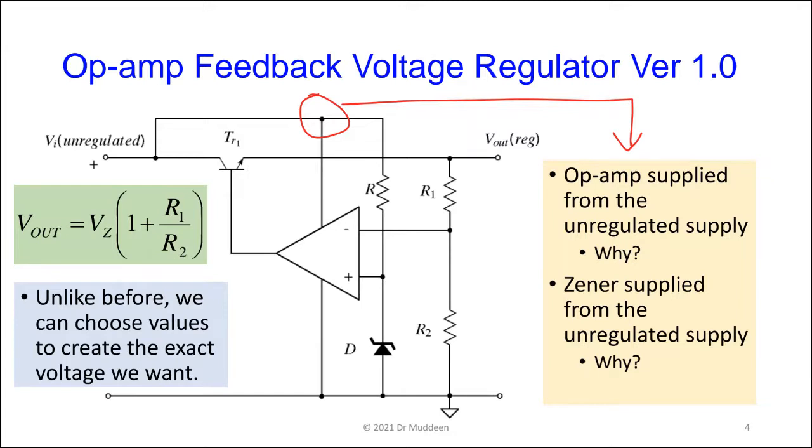The op amp needs to vary between two levels, exactly. So if I supply an op amp with, let's say, a 15-volt supply, what is the maximum voltage output that I could typically get from the op amp? If you remember your op amp discussions. Anyone remember? Okay, so the answer is less than 15 volts.